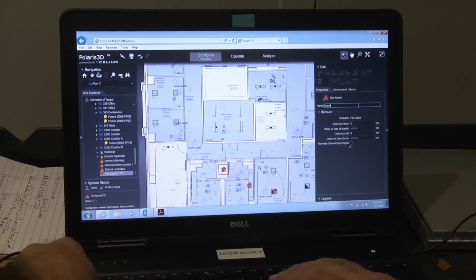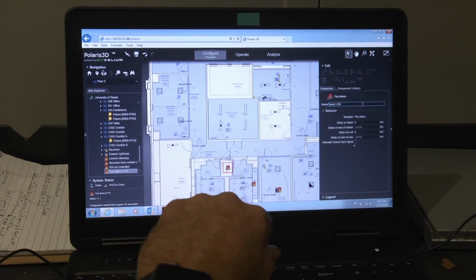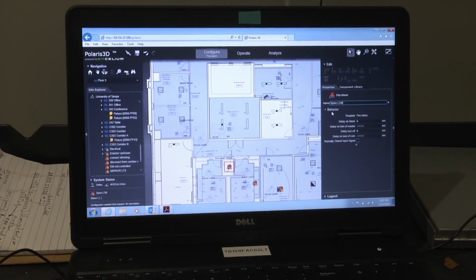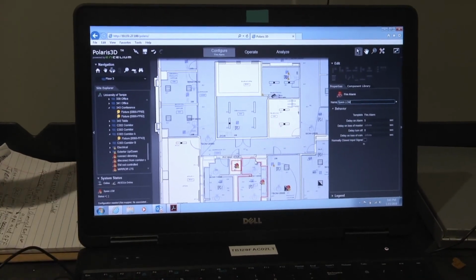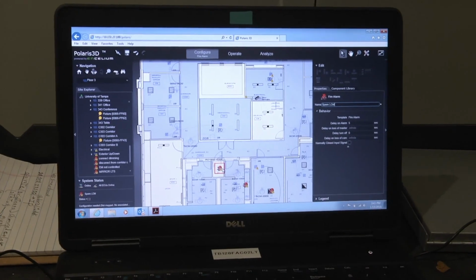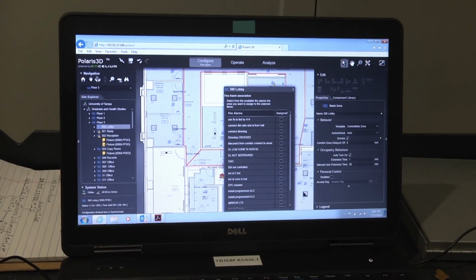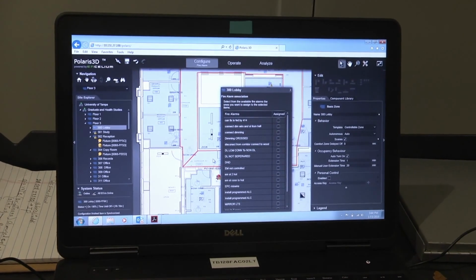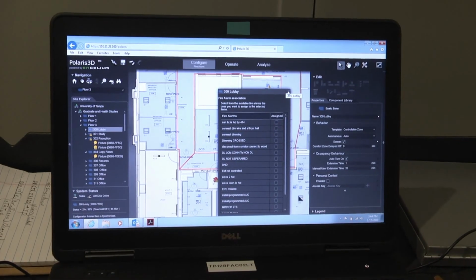LCM, it looks like. Spare LCM, okay. And that's just putting a note there. So when you look at the floor plan and see any fire alarms, there are usually notes that mean something is going on that you're going to revisit. So this is a quick step for you to add an actual fire alarm, not necessarily as a fire alarm, but just a note-taking method. You put it there, and then you just hit save and configure again.